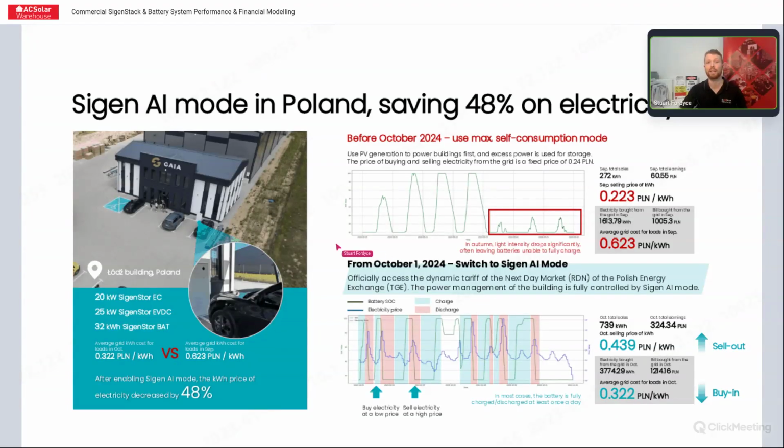Another cool feature that Sigenergy offer is, we talk about arbitrage, where if you've got a demand tariff you can charge when the rate is low and discharge when the rate is high. And if you've got a fixed tariff structure, that's something that's easy to program. However, you also have your own consumption, you have weather patterns that change your production, and there's a lot of moving parts. And if you set your battery up to just do arbitrage and you're not using it yourself, that's fine.